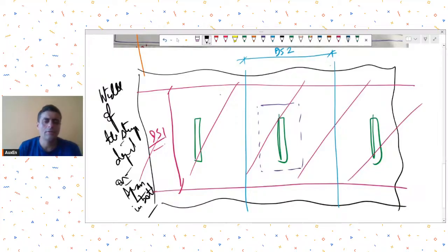So what you can do is, in software you can just model these strips having this width, which will depend on the spans in both directions and the sizes of your elements. For this you could take help from some codal references where they tell you what shall be taken as an effective strip width. So you take that strip width, and what do you do?